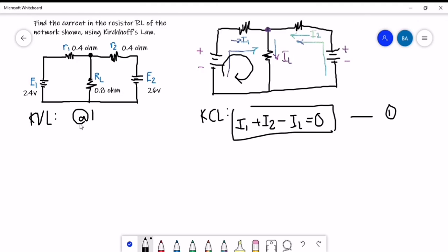we can find out the first equation using our first law, using the Kirchhoff's voltage law. So here, let us now apply the KVL, the principles that I have discussed earlier about the KVL. Where you exit, that is the sign of your voltage source. So here, the sign for our E sub 1. Since you enter in negative and then you leave at the positive terminal, then we could say that it exits at the positive terminal, then that will be a positive E sub 1.